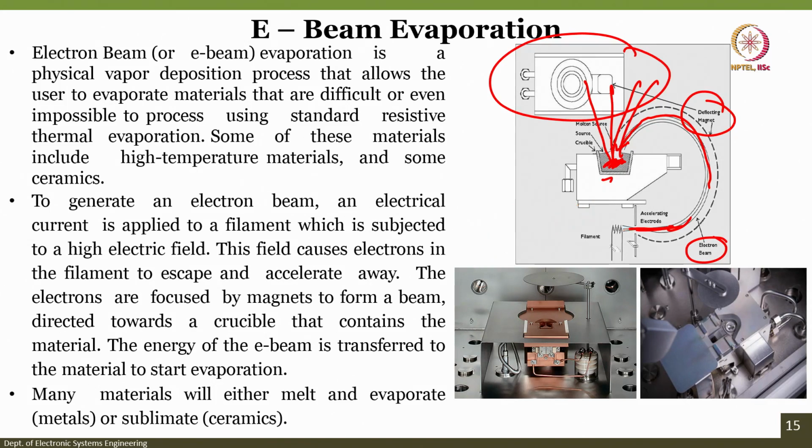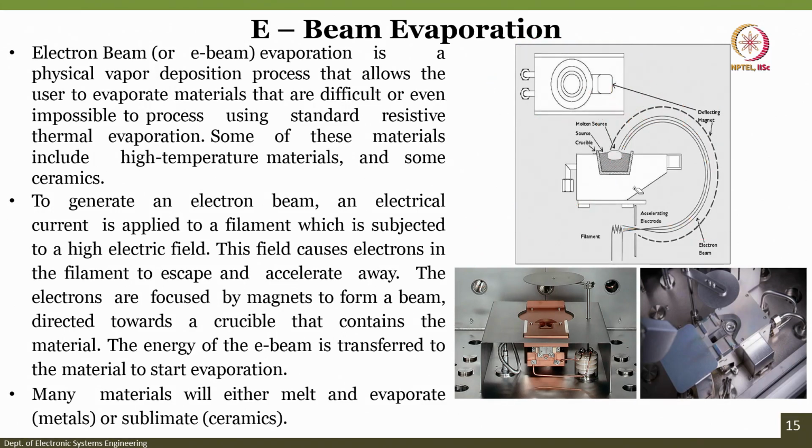Now, if you see the second schematic here, you can see how you can block the evaporation until you feel there is uniformity of the melting material. Here also you can see the same thing. This is the material; when it starts evaporating you can remove this plate from the evaporation site, and then you can deposit the material.